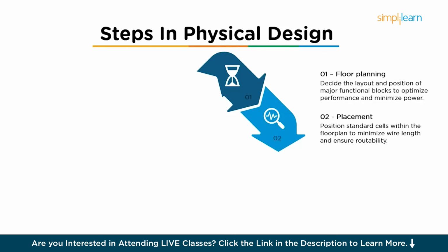The second is placement. After the floor plan is defined, the next step is placement. In placement, individual components like standard cells, meaning transistors and logic gates, are placed within the defined floor plan.